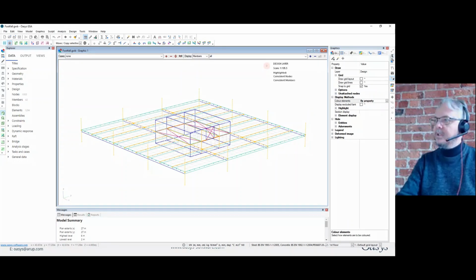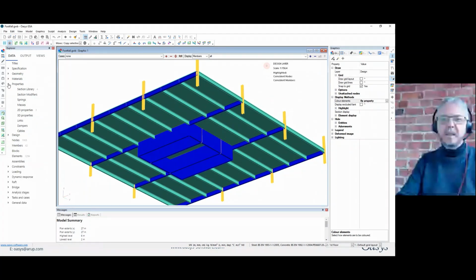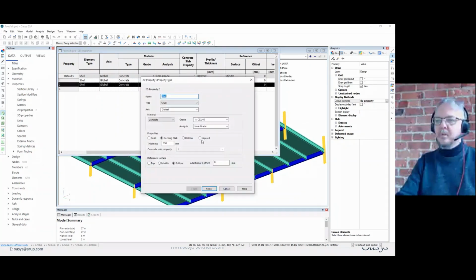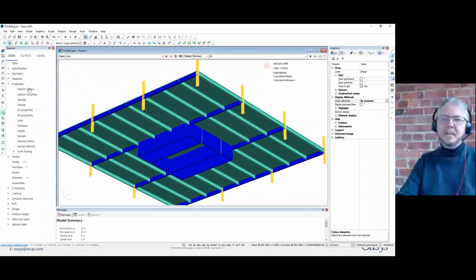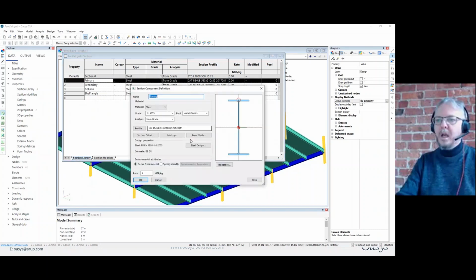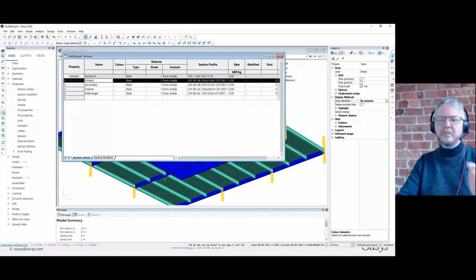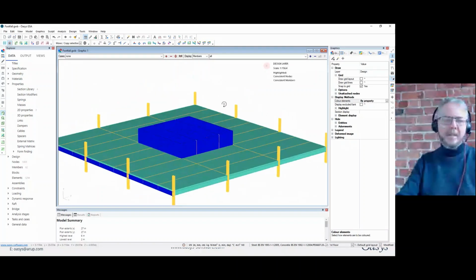I've also set up, actually, let me call up again, and you see we've actually got offsets set on the beams and slab. So, for example, the slab there, it is modelled with decking, and it's set to the bottom. Decking options are made available, and similarly in the beams, we have the beams offset to the top. Now, I would recommend against doing this generally, but when it comes to footfall analysis, when we want to get that composite action between the slab and the beams, this is definitely the right approach.